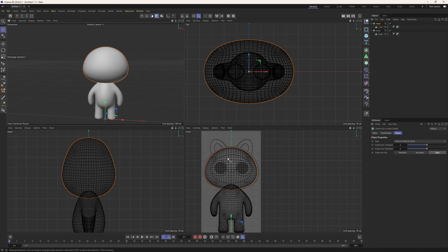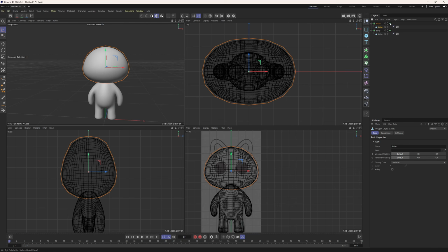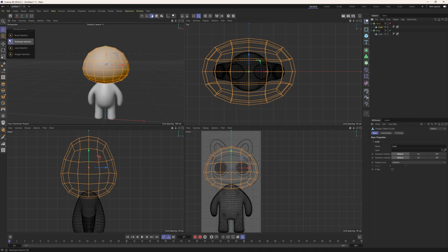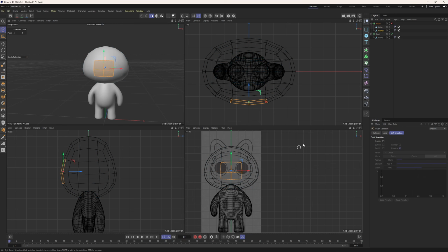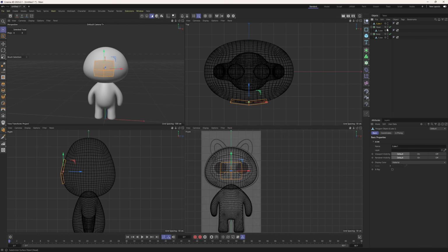Let's create a face mask around the cat's face. Let's switch to circular selection and select our original head geometry. We select 4 polygons in the middle and right-click, Split. We are taking it out of the subdivision surface, as one subdivision surface modifier can only work for one piece of geometry. We need to create its own subdivision surface modifier for the face mask.